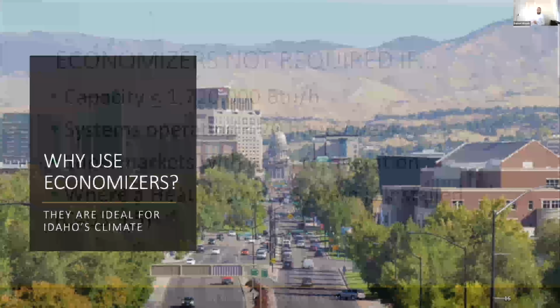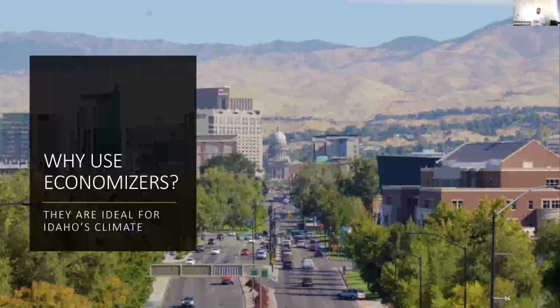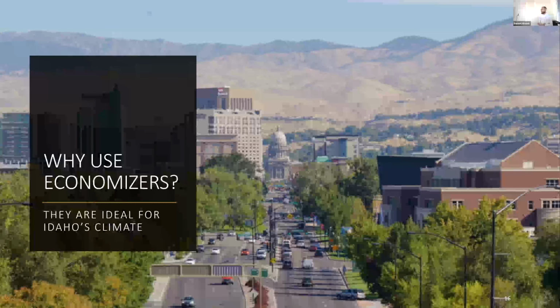But why do we use them? They're really good for Idaho's climate. So it's a way of just opening up and allowing outdoor air to do free cooling for you, rather than taking, you know, the exhaust air that's coming out of the building. That's, you know, during the summertime, say, maybe 75 degrees, but outside in the mornings, it might be 50 degrees. So instead of trying to cool that 75-degree indoor air down, just exhaust all of that and bring in all this fresh, cooler air, so you minimize your chiller requirements.